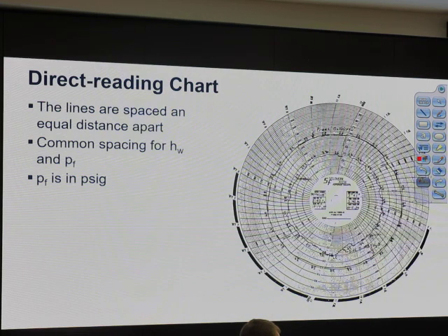So you hardly see these charts anymore. Instead, there's a flow computer up there about the size of your iPhone. It sits up there doing that integration, taking those signals as they come across the orifice plate, integrating them and giving you a digital readout. That's electronically what's happening with the mechanical signal.